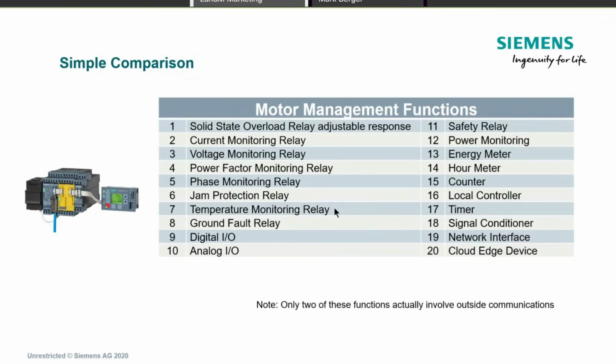Temperature monitoring relay. Let's move on to that. It's key that we take some of this data and use it not just to monitor the motor, but to monitor the process that the motor's turning. Case in point, you have a gearbox and nobody's looked at it for a while. Maybe the PM hasn't been done for a while and the oil in it has leaked a little bit or something to that occasion. And with the turning of that gearbox, it's overheating.